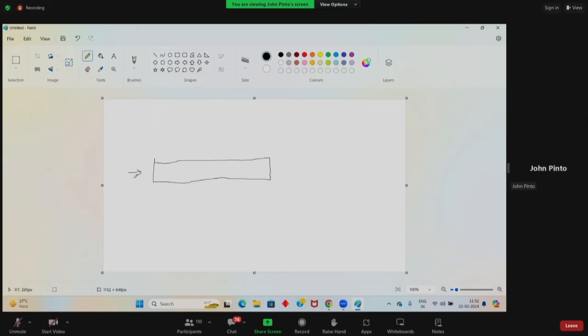Our idea is to see how the concentration of the scalar will change with space, because as it is moving ahead in time, it is also reacting. So its concentration at the inlet is 1. As it moves ahead, its concentration will decrease. But we want to monitor concentration at any one section. So concentration at one section will be uniform if my velocity is uniform throughout.